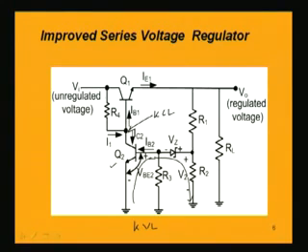One current is coming through R4; let us name it I1. I1 is the incoming current, IC2 is the outgoing current, that is the collector current for the second transistor, and the other outgoing current is IB1, which is the base current for the first transistor.